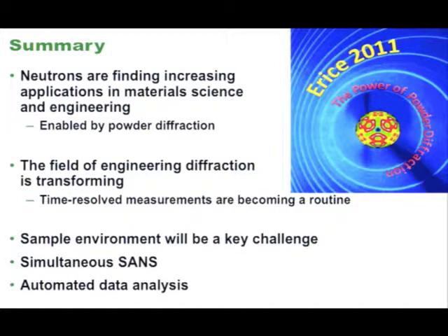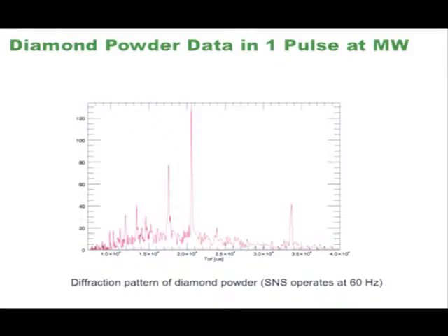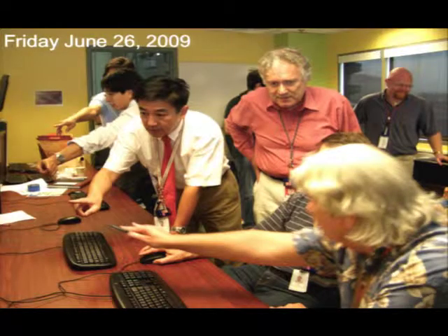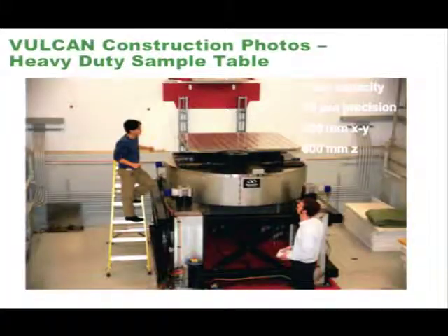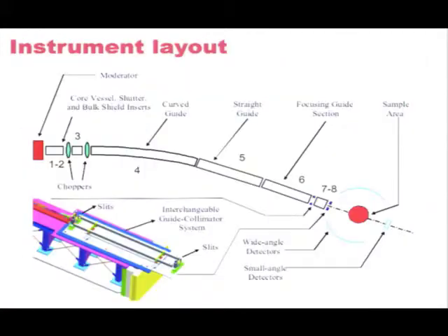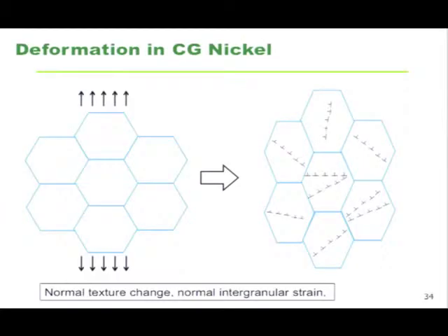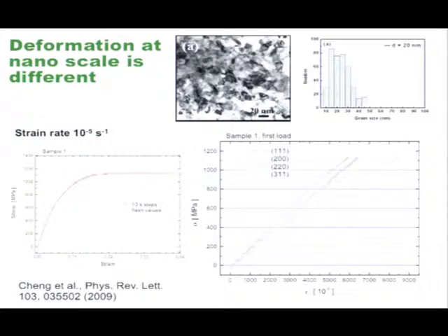It's well known that what you were measuring was creep deformation, not elastic deformation. And it is well known that when you decrease the crystal size, there are even plots that show what is controlling the deformation, whether it is grain boundary sliding or plastic deformation. For every material, there is a plot in which you should know, based on temperature and grain size, what you get.